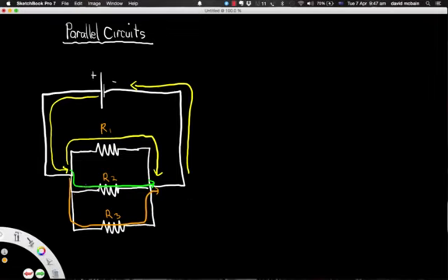This is a series of parallel circuits. So that no longer applies, because the current at this point here will equal the current coming out of the battery, but the current in this branch here will not equal that, because some of the current's going to go through this one resistor and some of the current's going to go through this resistor. So the current going through each of these resistors will actually be different if those resistors are different.